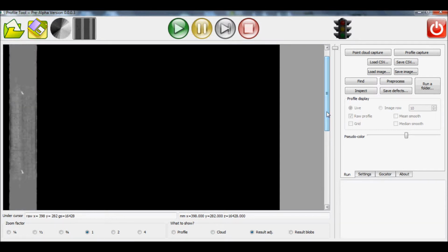but now this is in the true image of inspection. And what we're doing here behind the scenes when we hit pre-process is evaluating all of the pixels statistically, calculating a nominal surface and throwing out outlier points and data, and we get this self-referential perfect surface. So with that we can subtract the original surface from it, and we get this model that creates an image to locate and measure the defects.